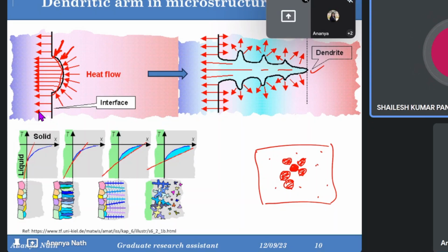So if we have undercooling, if delta T is more, then delta GV is more and delta G star becomes less, and that delta G star limits the lesser size at which the grain can be stable. Always remember, undercooling and supercooling are okay to understand, but high cooling rate and low cooling rate are both different phenomena.